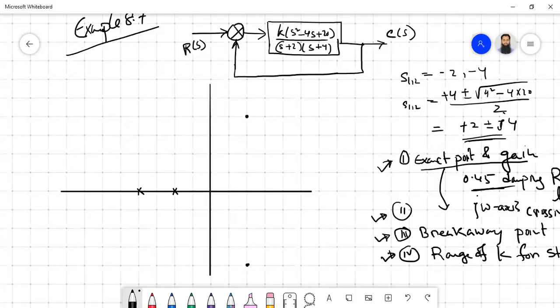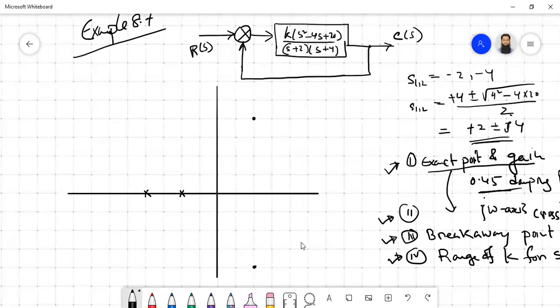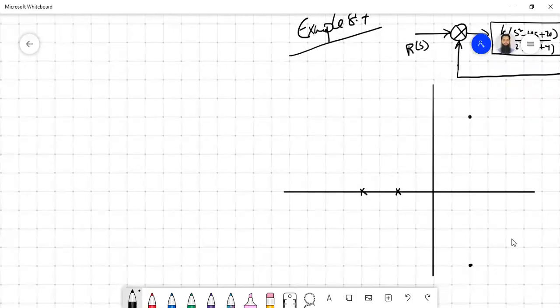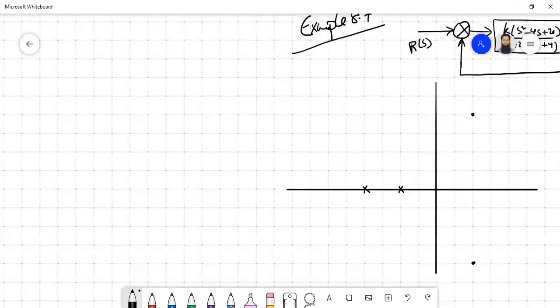So now we know that the poles will merge together at the breakaway point, and then go towards the imaginary axis to find their soulmate in those two zero locations. To refine the diagram, the next step should be to find the breakaway point.